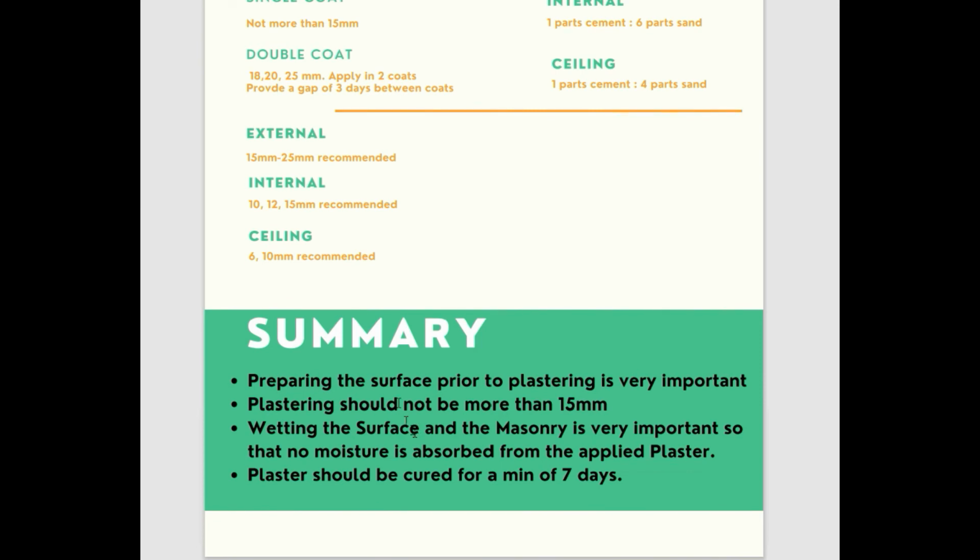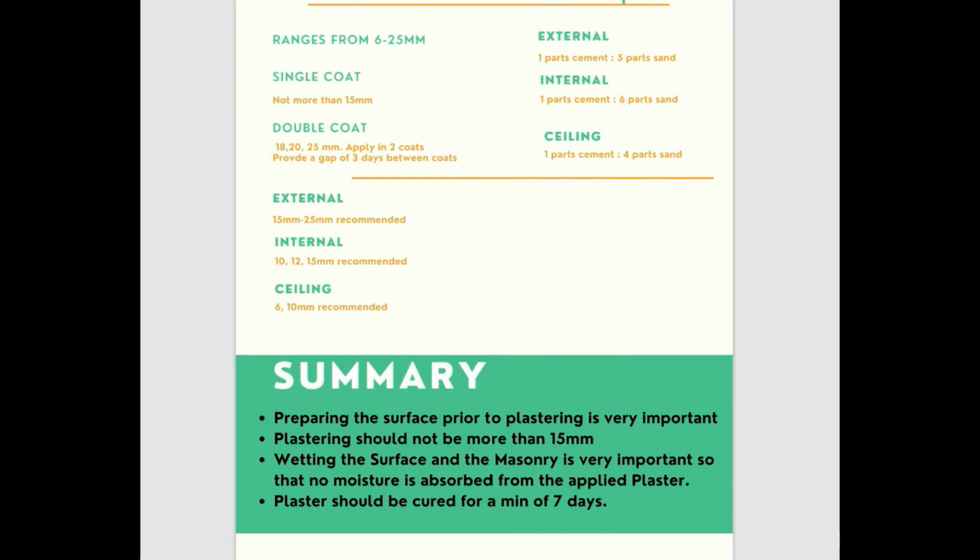All right. And the third point is wetting the surface and the masonry prior to plastering is very important so that no moisture is absorbed from the applied plaster. And the last point is plaster should be cured for a minimum of 7 days. So a 7 days curing period is recommended. So this was the small infographic we have regarding plastering.